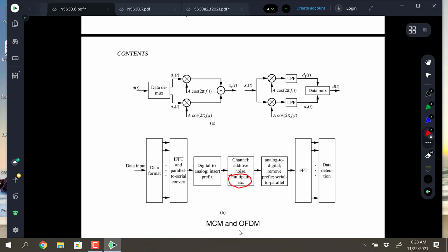So you're going to apply the modulation in the frequency domain at these different subcarriers, and that's what the input side is. You can think of data going on each of the subcarriers or each of the frequency bins, and then by taking the inverse FFT, you get back to a time domain waveform, which is this OFDM signal. And the cyclic prefix, like I said, we'll talk about what that's all about. That relates to multipath, though, and the use of the cyclic prefix is pretty much standard to mitigate multipath.